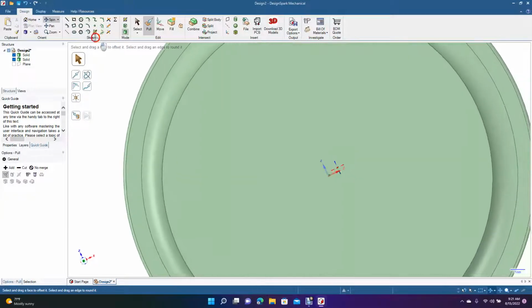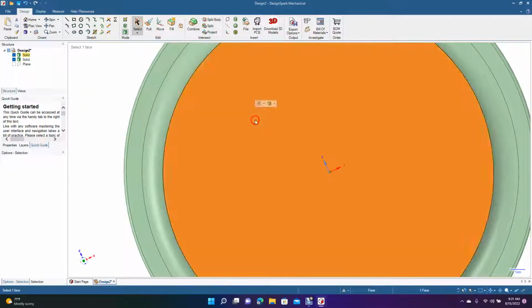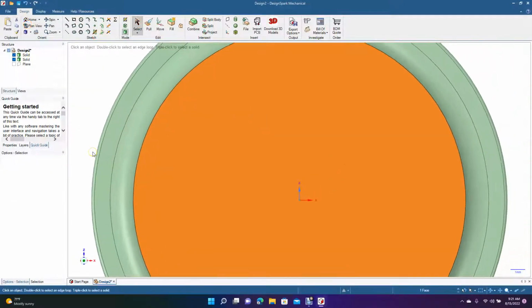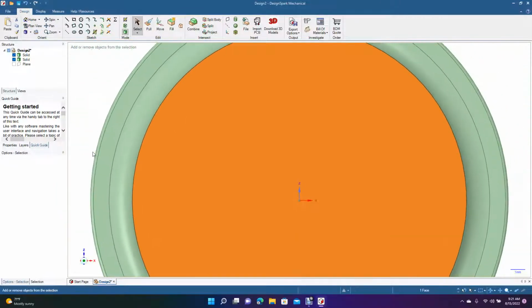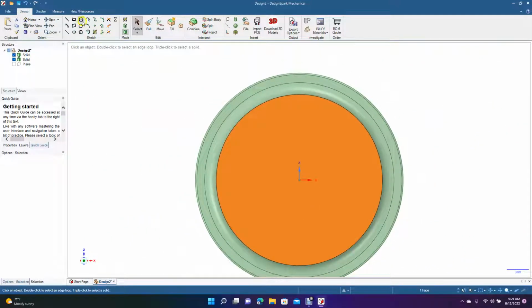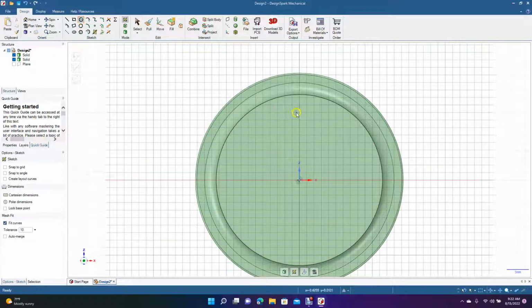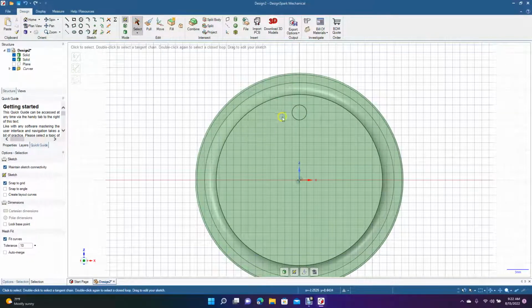Now we're going to spin this around and put our feet on here, little pegs. Go to plan view. Let's Control minus. Okay, we're going to add a circle. Turn on the snaps. Go ahead and add these. That's too big. We don't want it that big. Let's go 2 millimeter. Let's go ahead and click on that circle.